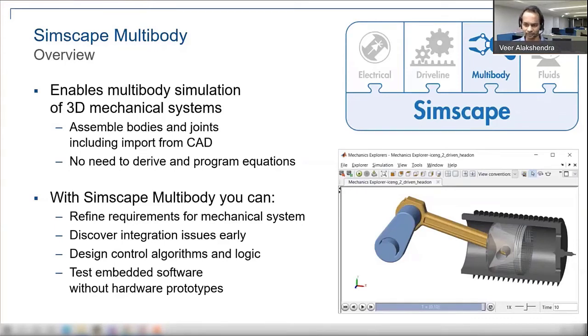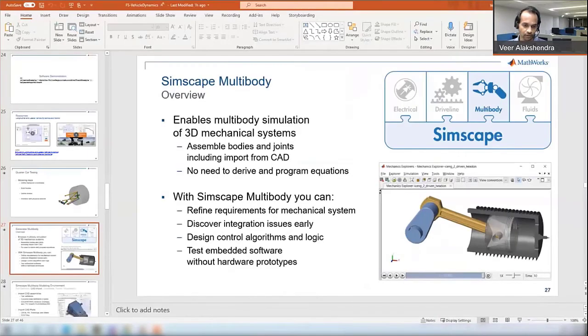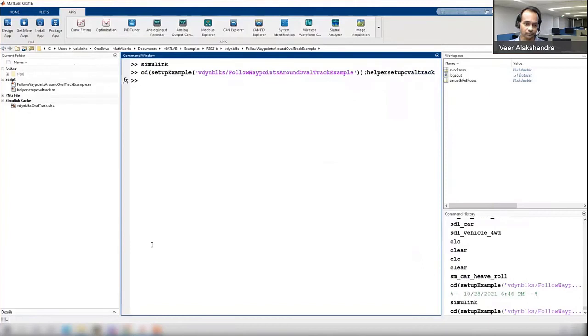Also, for example, here this is just an example of a piston cylinder mechanism. So in short, again, we'll see how, using solid blocks and different blocks which can define rotation and translation and even constraints and forces, we can model a multi-body system. So as an example, the suspension system. Okay. As an example again, if I close the Simulink library browser, not a problem.